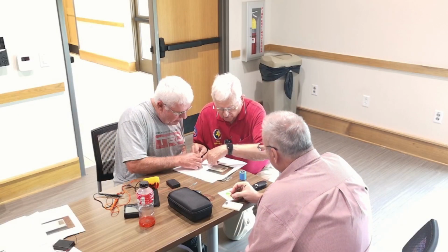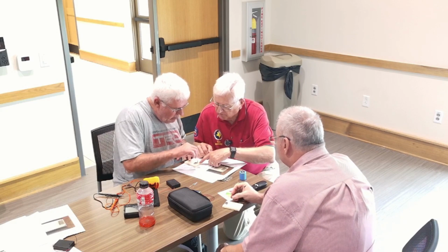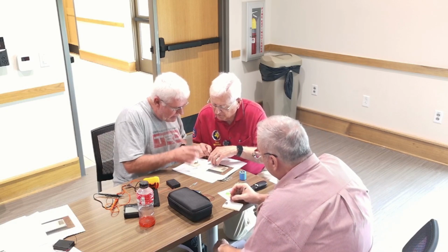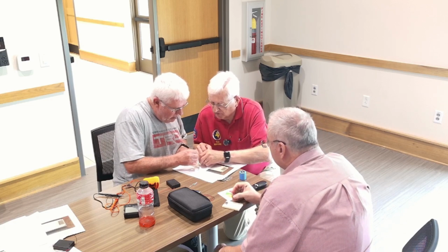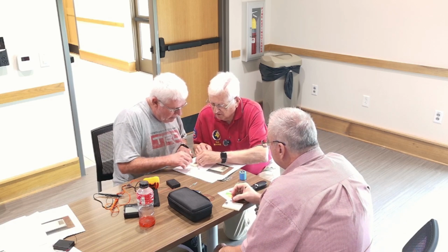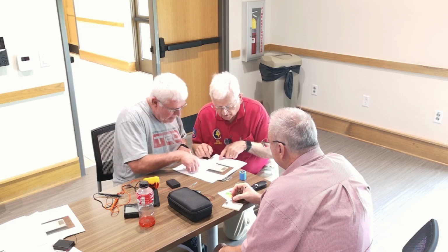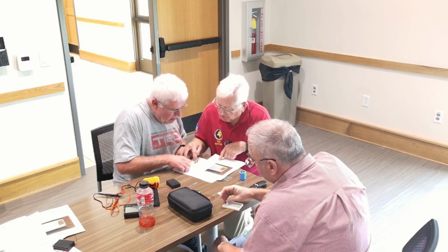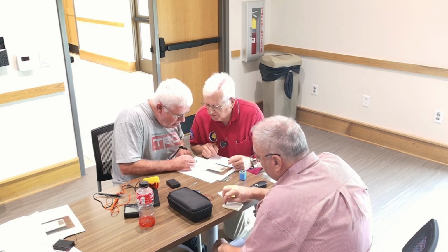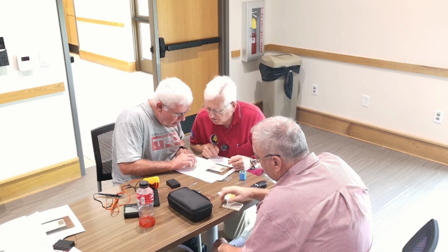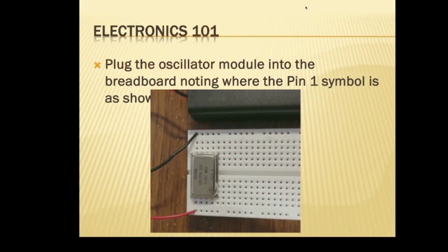Okay, and 14 is going to go to the plus power, so that's gonna be the plus power over here, right? Well, if you want plus over here, we'll just move this one over here. Yeah, we just move it right there. There we go. Okay, and then ground goes on pin 7. So we got 1 through 7 over here, so it'll be that pin at the end there. And it's 7 here, this way, one more. Right there. Got it. Okay, that'll give us power.